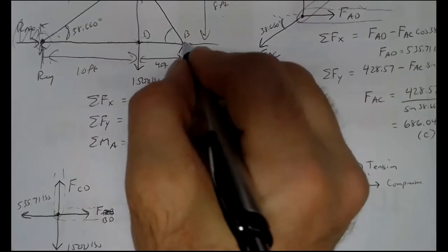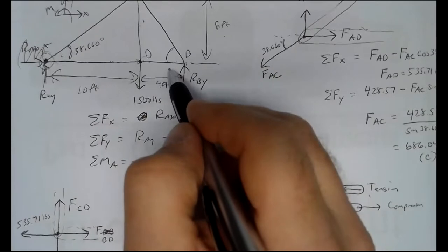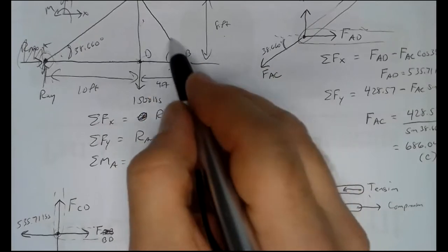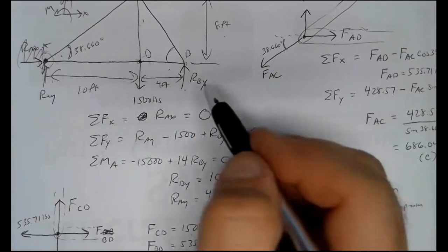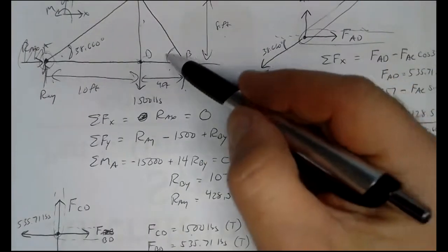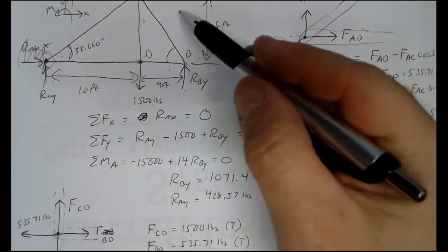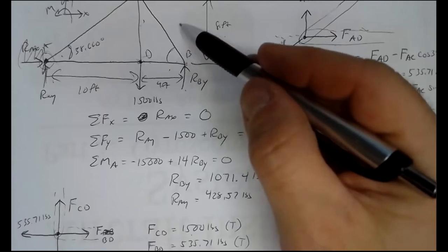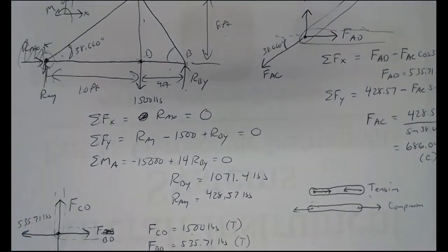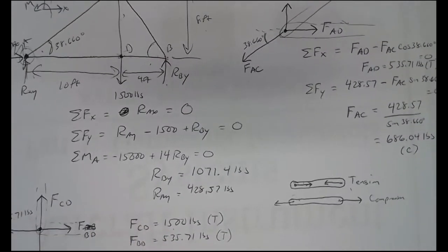Then we can do the free body diagram at joint B. You'd have to figure out the angle, inverse tangent of 8/2. And you'd only need one of the two equations, sum of forces in the X or the Y direction. I'd probably use Y because it wouldn't bring anything in that I'd calculate. Because in the Y direction, all I'm going to have is RBY and a piece of FBC. Could figure out what that is pretty easily. So I think we'll finish that one there, unless there are any specific questions on it.